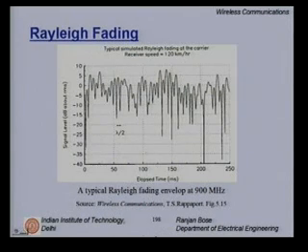If you look at the Rayleigh fading profile, on the x-axis we have the elapsed time in millisecond. Suppose a vehicle is moving along this axis, so the distance will translate to the elapsed time. On the y-axis we have the signal level, it is in dB, so it is a logarithmic scale, hence you have a well rounded profile, otherwise you will get a much more jagged received signal strength. So, the dB rounds it off.